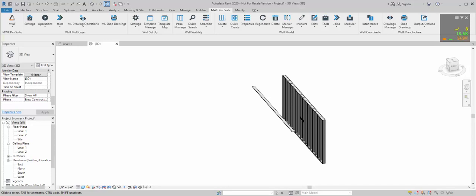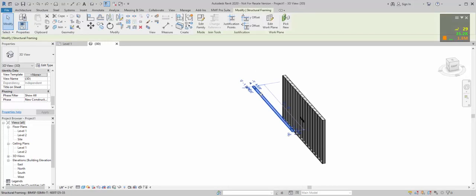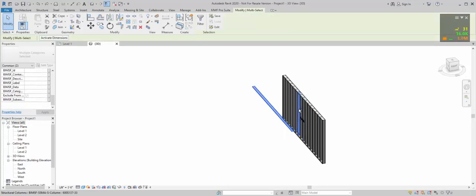This week we'll be discussing the Deflection Connector tool by stud member. Last week we discussed it by rule, which applied the connectors on each stud, and this tool will allow us to connect only one member at a time. And here is how it works. We'll begin by selecting our beam as well as our stud.